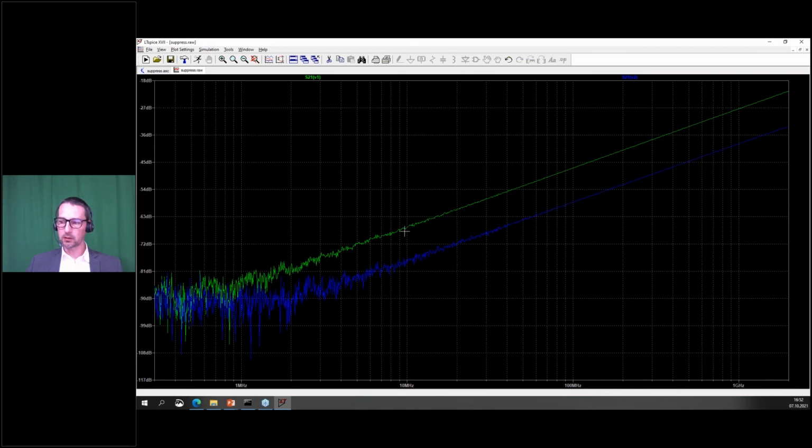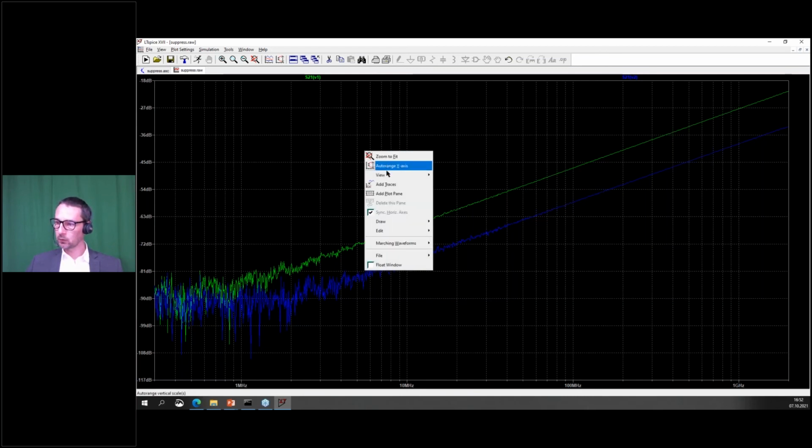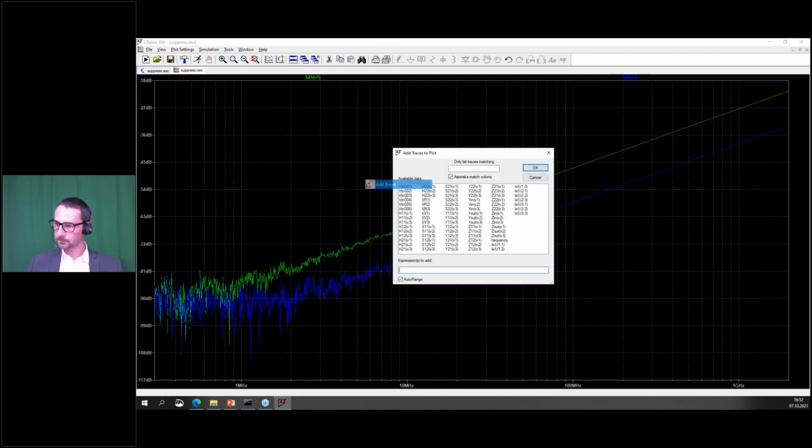So we did not only increase the distance now, but we also added the ground separation with the 2 ground pins in between, in the hope that this will get an even better result than only increasing distance. And we will see how this looks.